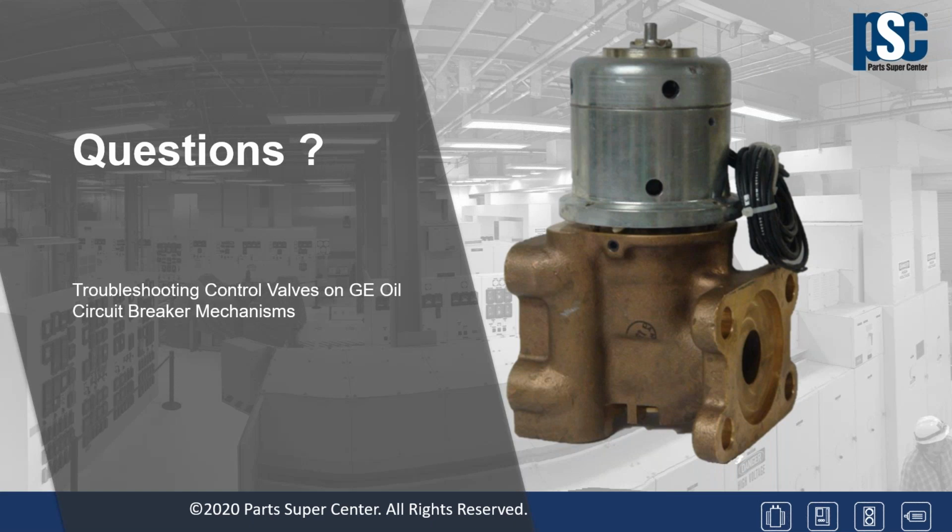So when you put the shims in, the metal shims underneath the cap that screws on the top, once you establish the right number of shims, you want to go ahead and adjust the number of paper shims such that you have just a little bit of compression on the valve coil such that it won't shake violently when it operates.